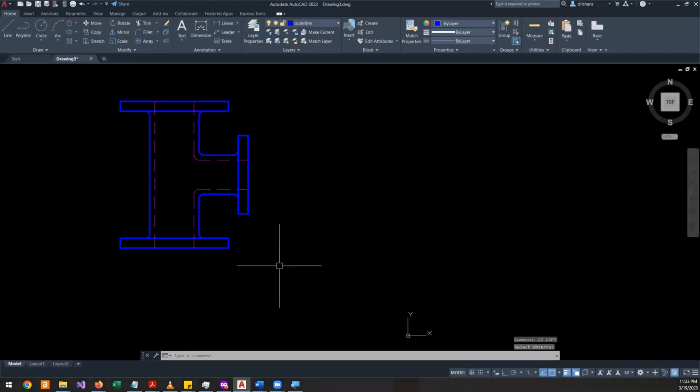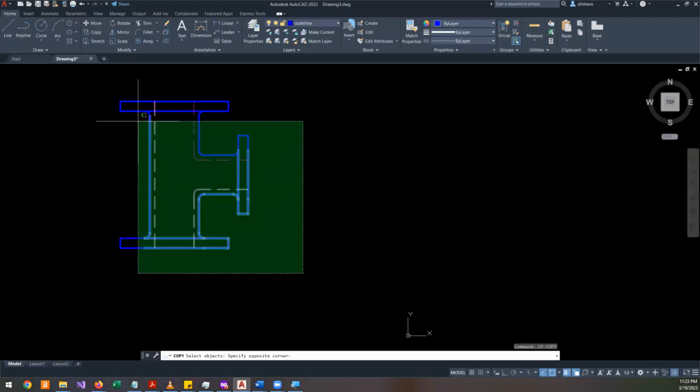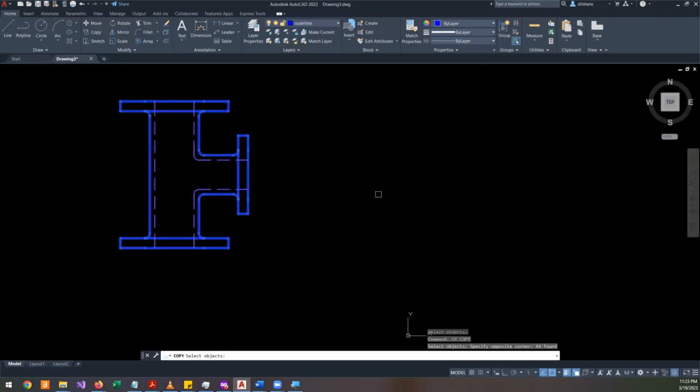Only one of them, don't type both of them. Just CO, or I type CP. Enter. Select whatever you want to copy. Enter.